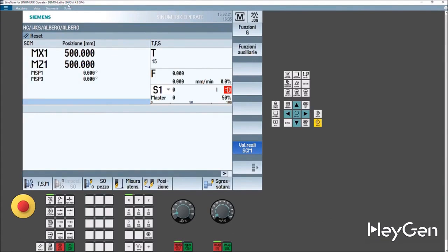It uses the CNCs of the 840 series from Siemens to learn ShopTurn. ShopTurn needs collaboration between your program and the tool table. Calling turret 3 with a tap and programming an external roughing operation causes an error. In ISO, the same program won't cause an error, even with a tap in the table, but you might have mounted an external tool. These precautions make ShopTurn less flexible initially, but it becomes interesting.